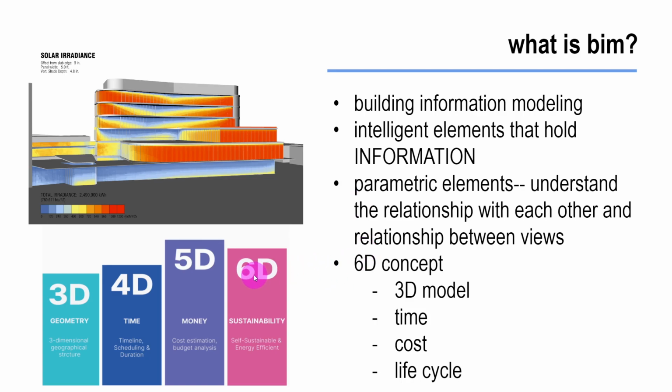Then industry-wise, one of the big benefits of BIM is what we call a 6D software. And there are even some people who relate BIM to 7D or 8D, but we're really only going to approach it within this 6D amount. And even then, we're not really going to focus a whole lot on the 4D. But what we mean with those 6 dimensions of this project is the first thing BIM covers is just the 3-dimensional geometry of a building. So I'll be able to see and understand the building on an X, a Y, and a Z relationship between each other.